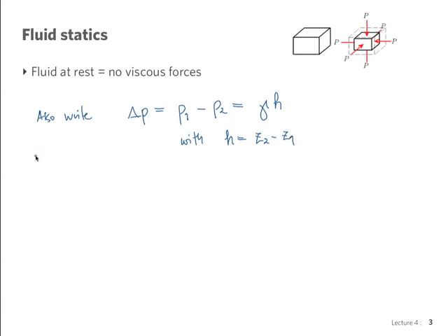So if we have a situation of a fluid, water, say, the surface of the water, usually when we draw engineering sketches that indicate a surface, an interface between, say, air and water, we use this little triangle. This little triangle just indicates that this is a surface under atmospheric pressure, like the surface of the ocean or the surface of a tank. That's all it means. Okay? So this is water here, and at the top there would be air.